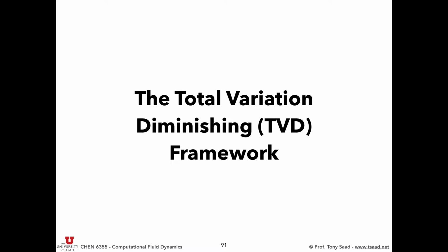So all methods that rely on a linear reconstruction within the control volume, and somehow for the QUICK scheme, they create these oscillations because the slopes create new minima and maxima. And we looked at one way to measure monotonicity, which was the normalized variable formulation, phi tilde, and then we went ahead and looked at the convection boundedness criterion, which allowed us to limit these oscillations.